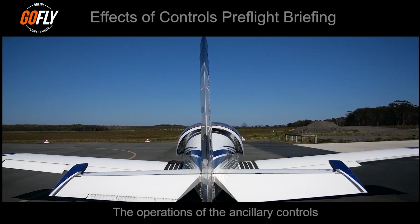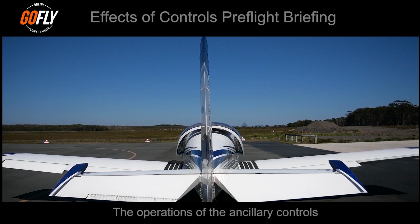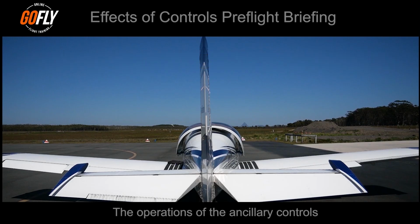A trim tab is a tab attached to a control surface, normally with a hinge, and can be attached to the elevator, ailerons, and rudder. They can be manually ground adjustable or in-flight adjustable. In most light training aircraft, only the elevator has an in-flight adjustable trim tab.